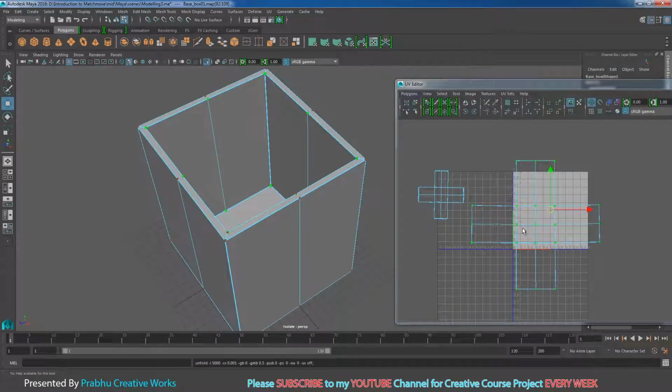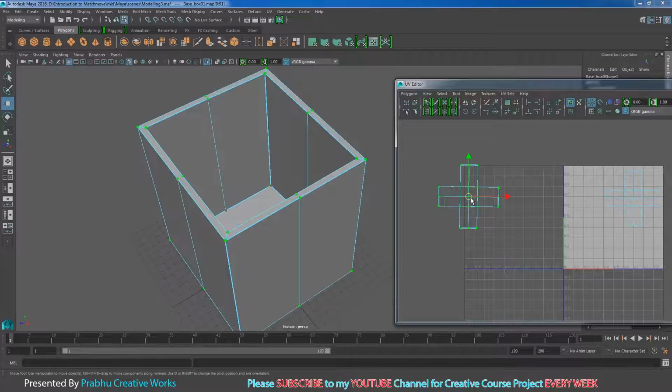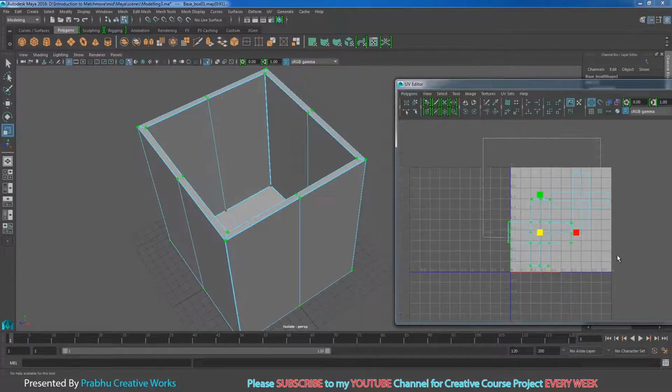So now the inner part will be unfolded. Press R, scale down in the middle, and press W. You want to keep this one a little bit inside of here. So I will select this UV and move this one over here, press R and scale a little bit bigger, and select both UVs over here and scale a little bit down, and press W and move a little bit inside.